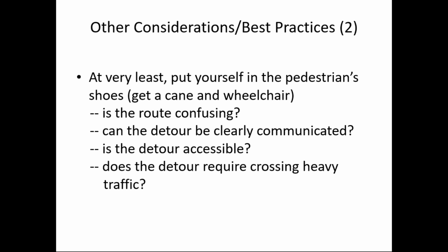One thing I also like to recommend is put yourself in the pedestrian's shoes. You or somebody working under you, get a cane, blindfold yourself, and walk through the project as a blind person would, and see if there's any issues. Or same thing, get a wheelchair. Manual wheelchairs are relatively inexpensive. Go through the project, the path. If the front wheels of the wheelchair leave the ground a lot, that's not a good thing. That means you need to relook at your cross slopes and surface and so forth.